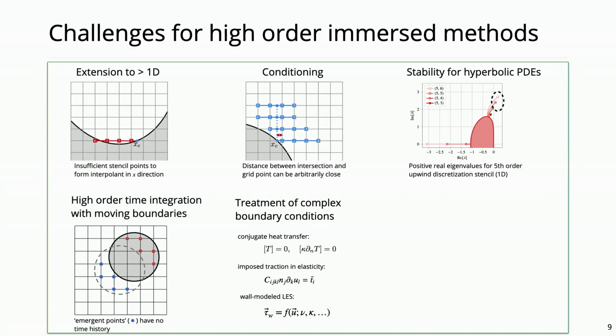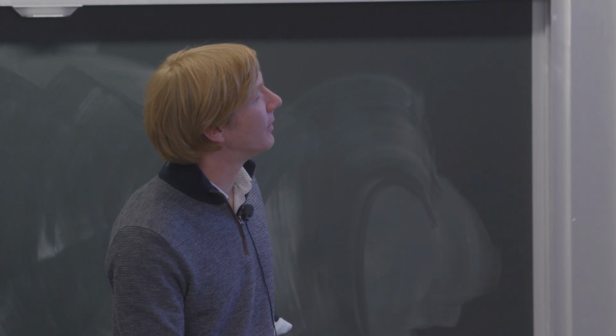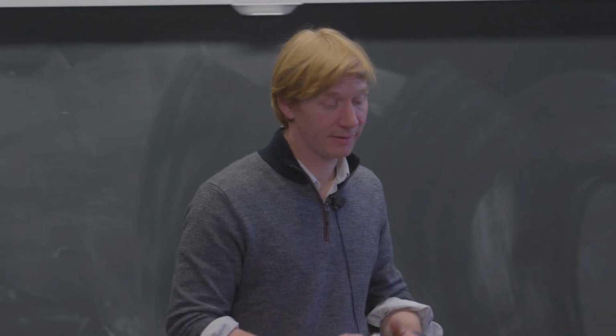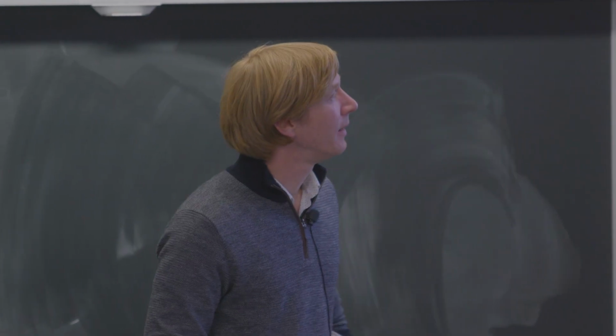Treatment of complex boundary conditions. If you want to apply this in real life problems, we have to tackle complex boundary conditions. For instance, in elasticity, we might have an imposed traction, and the traction couples derivatives of the displacement fields all together at a single point. And so if we want to create an extension of the displacement field, we have to couple all the components together across this interface to create the appropriate ghost values for every displacement component.